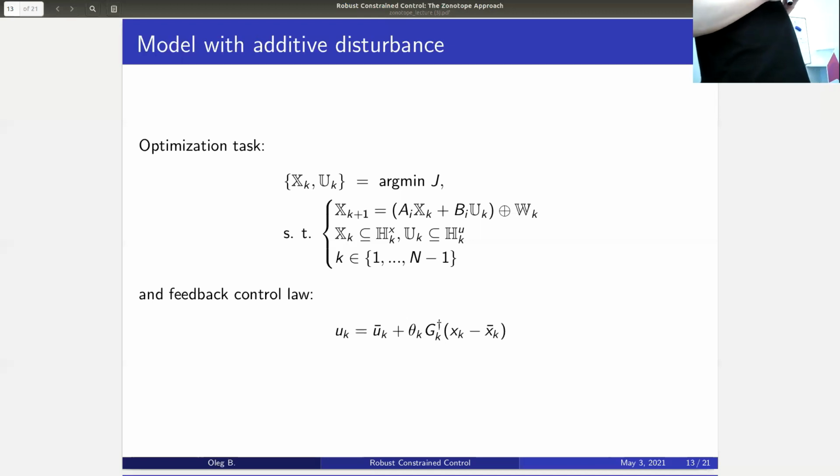But you need to see, and that is, by the way, a general point here: let's say you have a very small Zonotope, and you say from this very small Zonotope we are going to wait with this teeny Zonotope. The problem is, from this very small Zonotope, you could escape with a very small perturbation. And if you escaped, your guarantees are only inside the small Zonotope. So for example, you could have enormous gains because the gains are designed to react to very small errors inside this tiny Zonotope. And once you're outside of the Zonotope, your guarantees go poof, right?